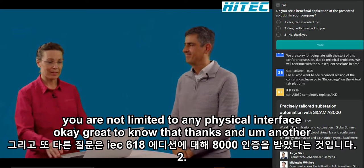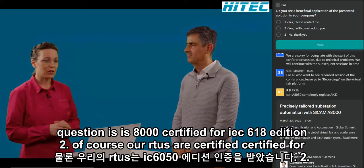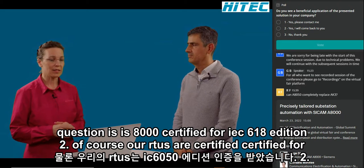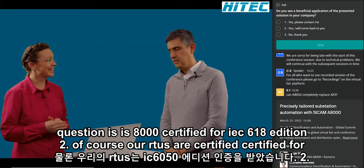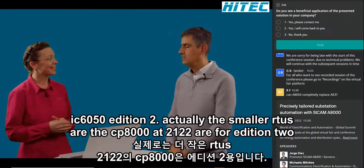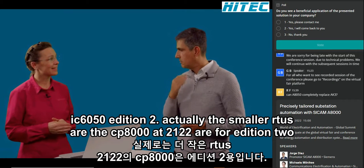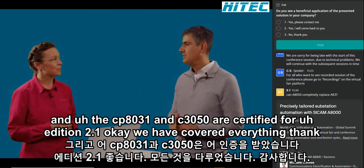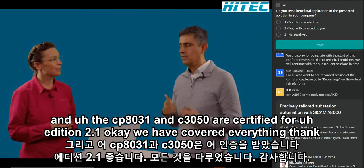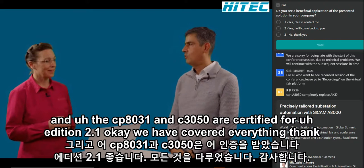Oh, okay, great to know that. Thanks. And another question is: is A8000 certified for IEC 61850 edition 2? Of course, our RTUs are certified for IEC 61850 edition 2. Actually, the smaller RTUs, the CP8000 8021 and 8022, are for edition 2, and the CP8031 and CP8050 are certified for edition 2.1. So okay. We have covered everything.